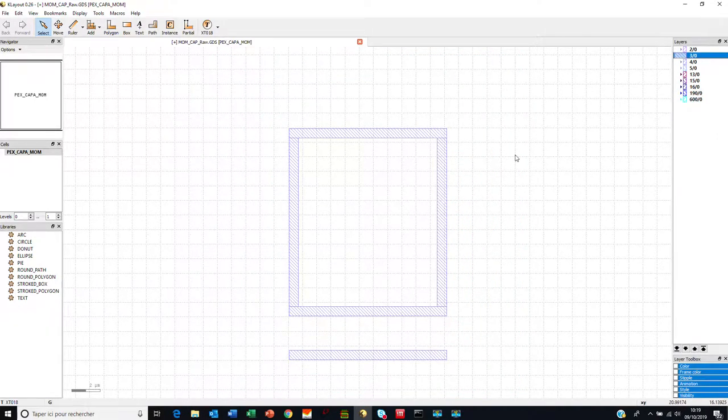Next step is the active or diffusion layer present in layer 3, which defines the places where silicon comes to the surface. And in the places where no diffusion or active data is available, we have a shallow trench isolation, but it is missing in the GDS. So again, we have to generate it.